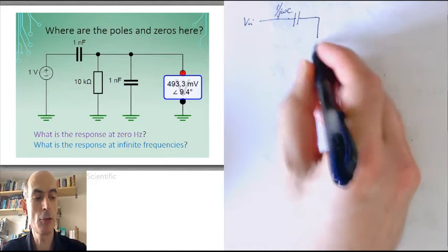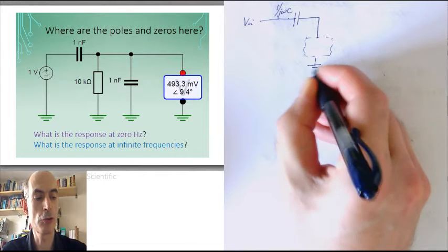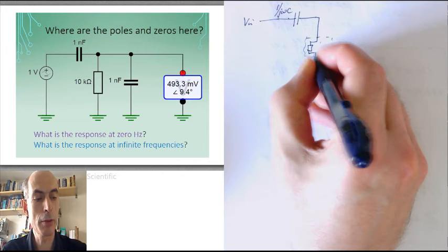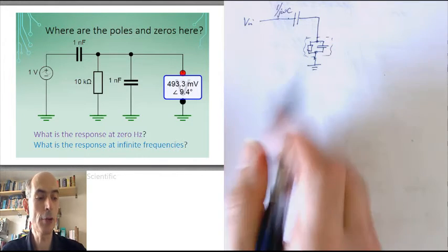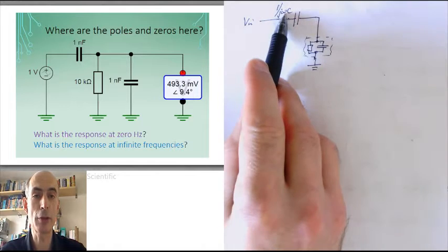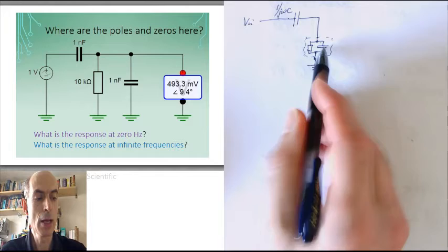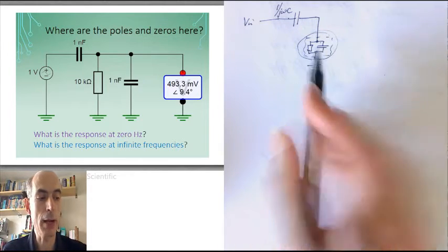And the impedance of this element down here, where we're taking the output voltage of, is a resistor in parallel with a capacitor. It's the same value of the capacitor up there, so that's convenient. I can just call this 1 over j omega c as well, and apply the general formula for the impedance of two components in parallel.